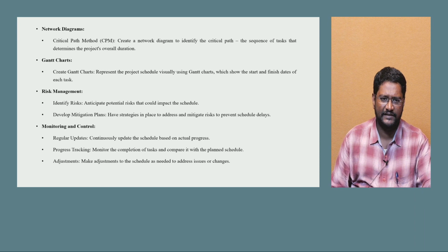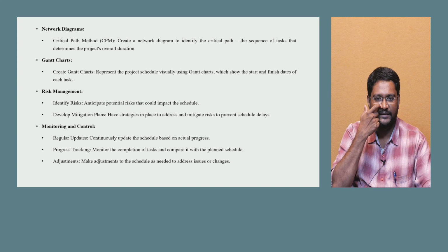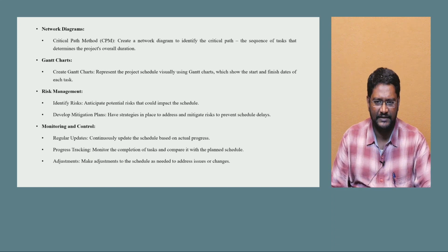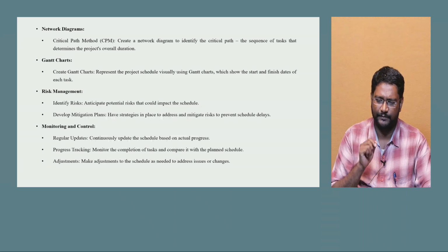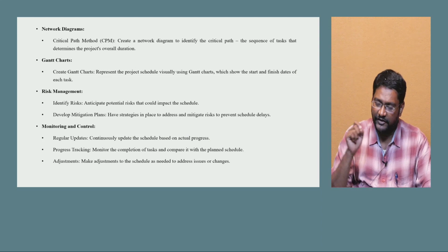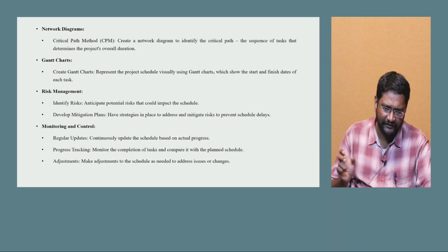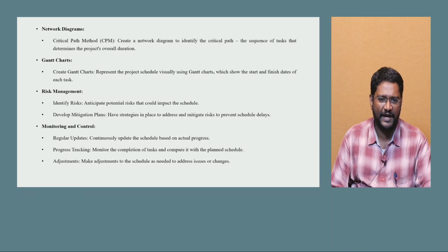Okay, next Gantt charts will be there. The charts also we have to develop for the scheduling. Create Gantt charts to represent the project schedule visually, which show the start and finish date of each task. So for example, the first breakdown is there, first plain cement concreting is there, when we are starting, that has to be mentioned here. When you are going to end, and what is in between, what we are going to do, that will be given here.